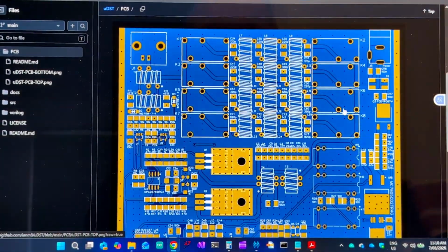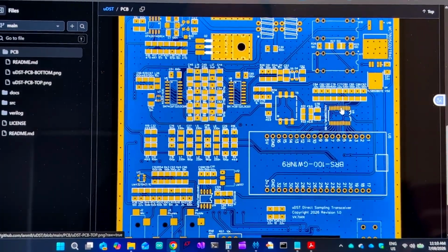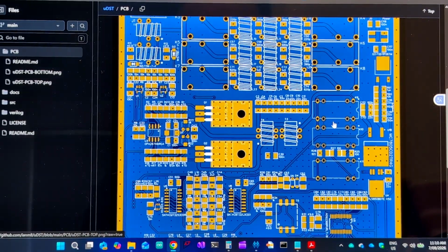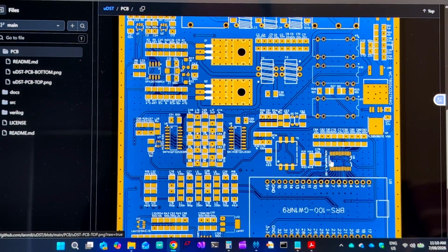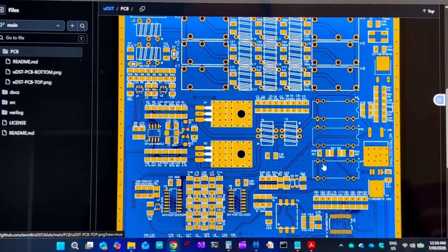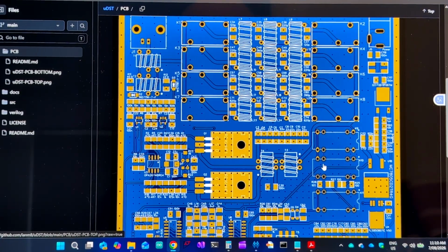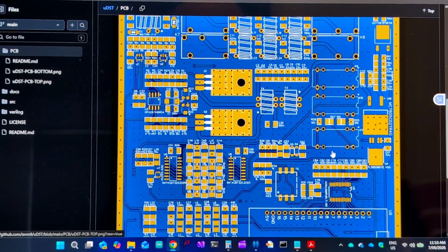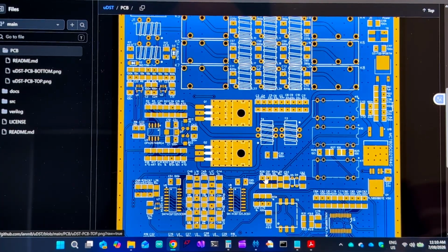Now, I've designed the printed circuit board, revision 1, and I'm not going to go through it all. I do follow some strict rules when I design a board. Always at least 4 layers. Inner layers are ground plane. Plenty of stitching vias and a ground via for each device that's connected to ground itself.